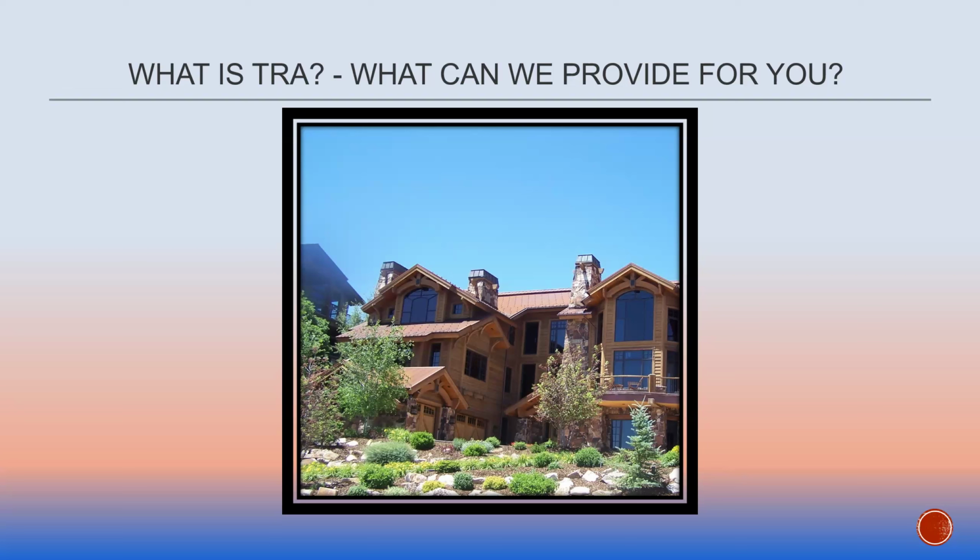If we don't install it and there's a problem, what could that problem be? Is it just going to be a deck railing? Is it going to continuously fall on these people's hot tub? Is it going to fall directly in front of their garage and they won't be able to get in and out? Just considering that risk versus reward, because there are some houses or buildings where snow retention just does not make sense, and that's okay. But it has to be a conversation with that client.